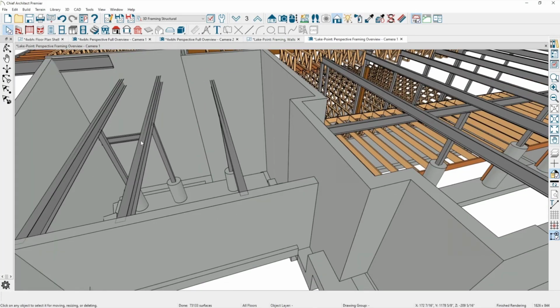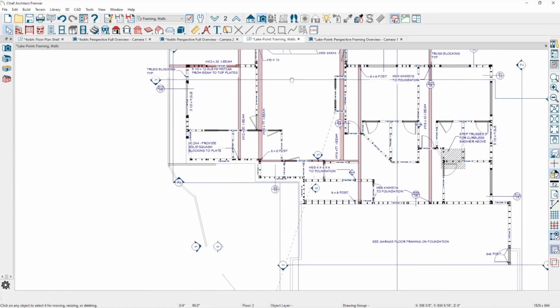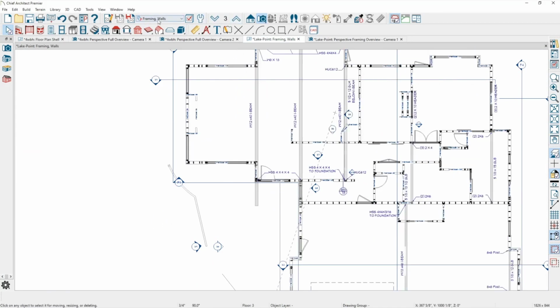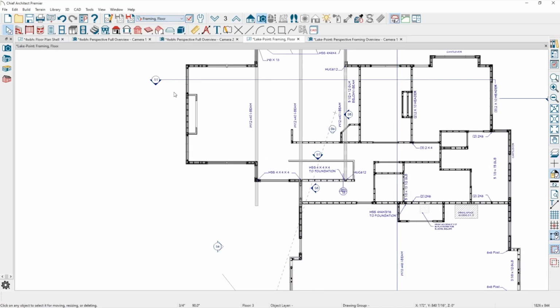So in this case, you see these beams out in front here? That's going to be carrying actually earth, and it's going to be sloped. And the way that was handled, I believe, first of all, you can't slope those unless you use a polyline or a solid tool. Let me switch over into, is that the framing for the floor?